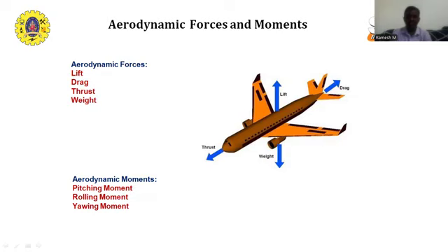The aileron is a primary control surface which is responsible for the rolling moment. But for pitching moment, which means the nose up and down, it is taken care of by the elevator. That motion is called pitching motion, so the moment produced is called a pitching moment. So the elevator is a primary control surface which is responsible for this pitching moment.